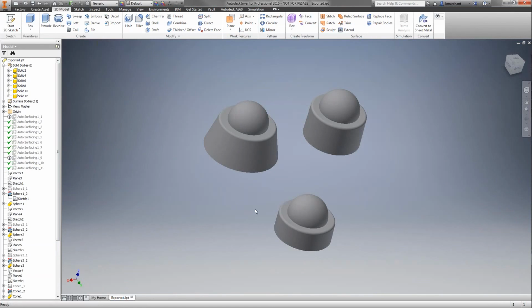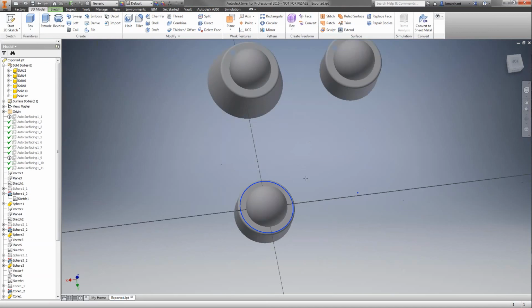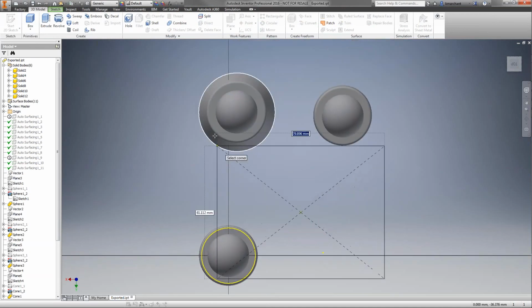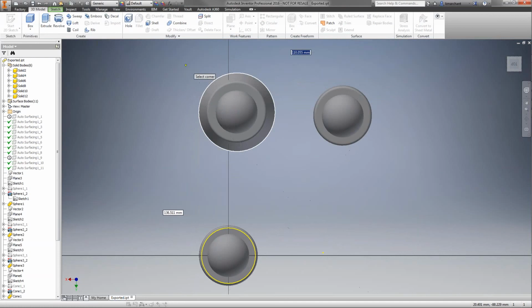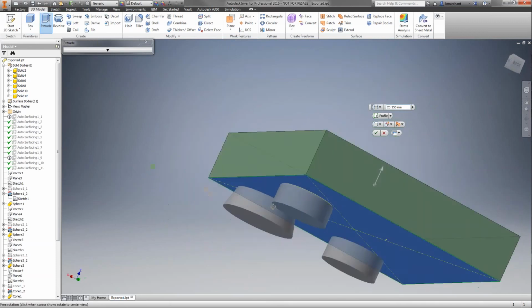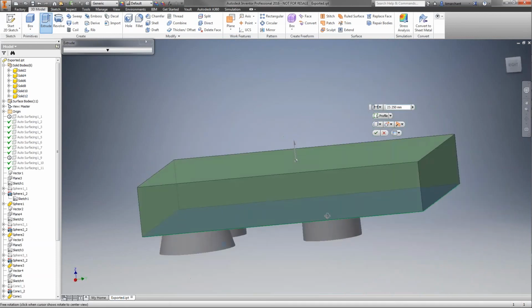So now I've got to put my geometry on there. I've got to start my part. So I'm simply going to come out here. I'm just going to throw a box out here, and I just want to make sure this box covers everything that I've got. I'm going to make sure this is a new solid. I can see that I incorporate all of that information.